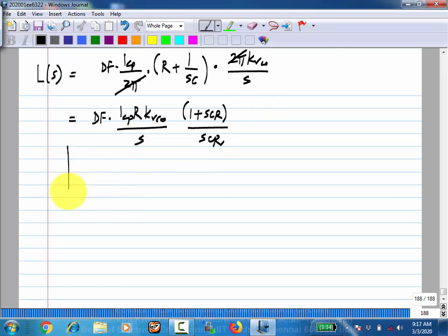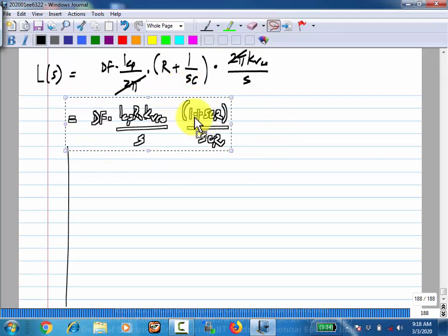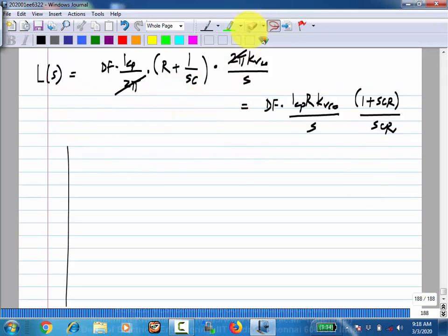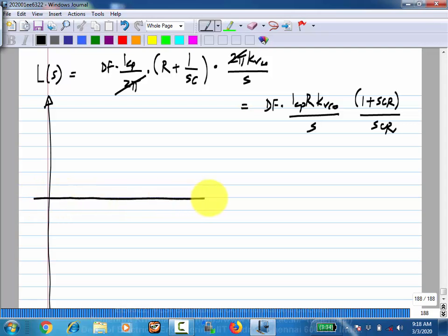So what does the Bode plot look like? There is a reason I decomposed it like this. What is the Bode plot of the first part? It's just an integrator, minus 20 dB per decade. And then, where does it cross unity? This number, okay?